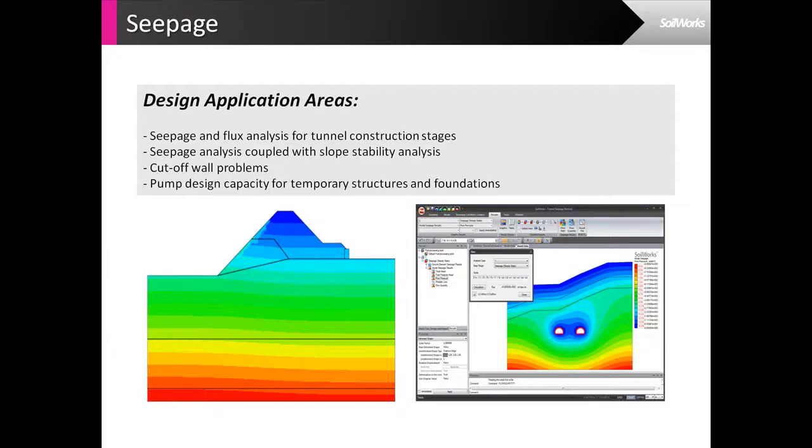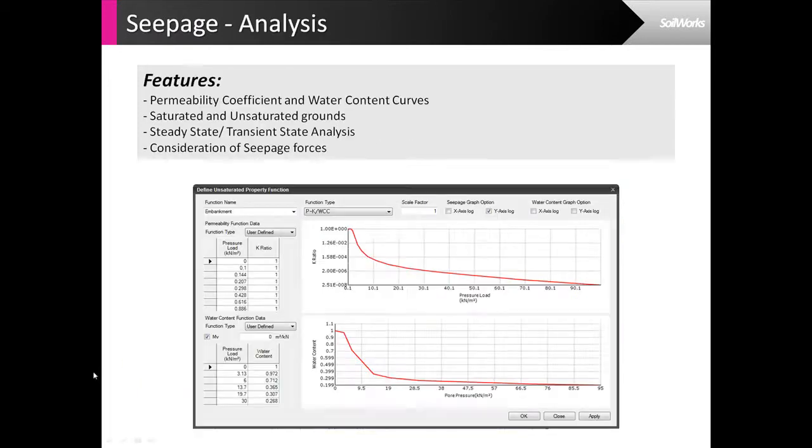We also have the Seepage module, which can be used for seepage analysis and also flux analysis for tunnels, construction stages, and also we can couple it with the slope stability analysis. We also have pump design capacity for temporary structures and foundations. Some of the features of the Seepage module is that we can specify saturated and unsaturated grounds. We can have steady state and transient state analysis, and also we can consider the seepage forces.